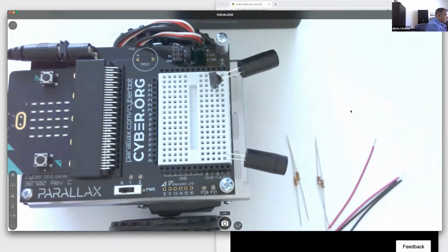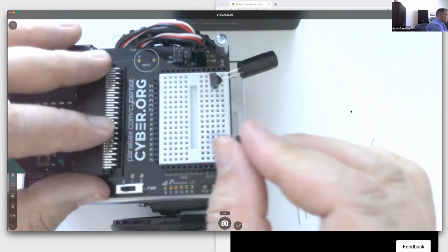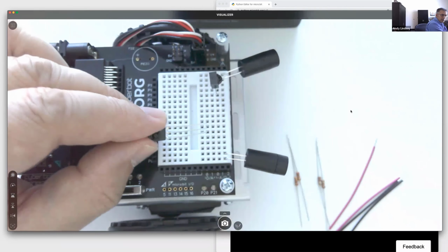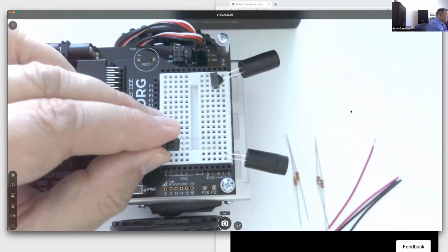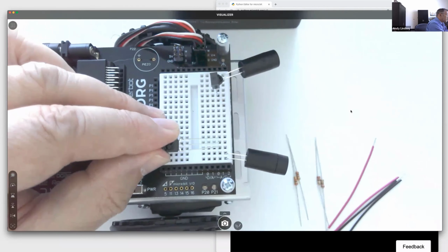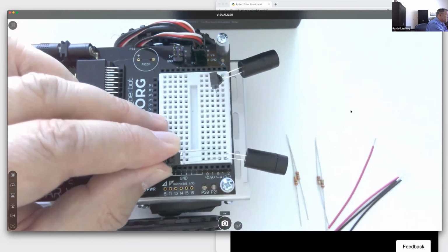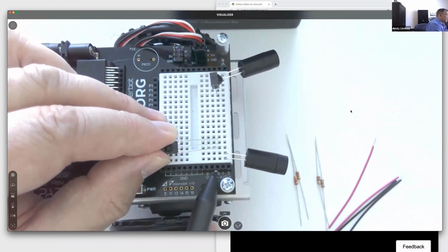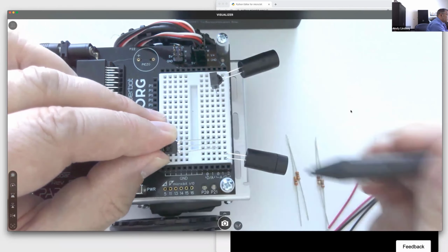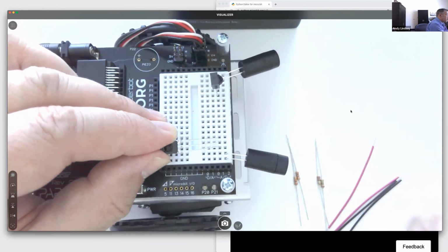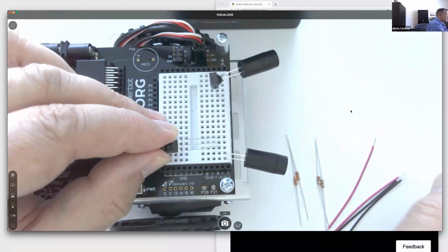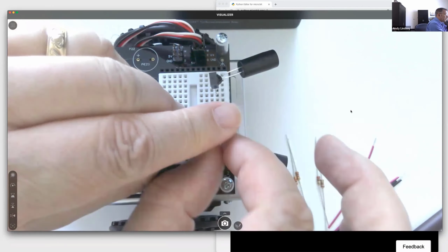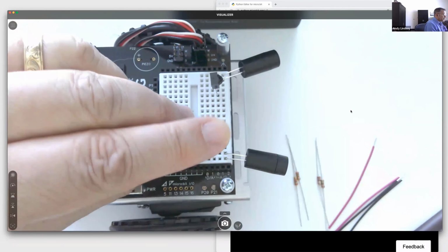A reminder to make sure that all pins you plug in sink in about 1/4 inch. We want to be the next row up from the 2 infrared LED pins, so rows 1, 2, and then 3, 4, 5 on the bottom is where the lower of the 2 infrared receivers gets plugged in.